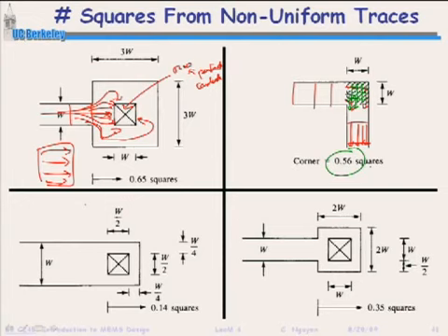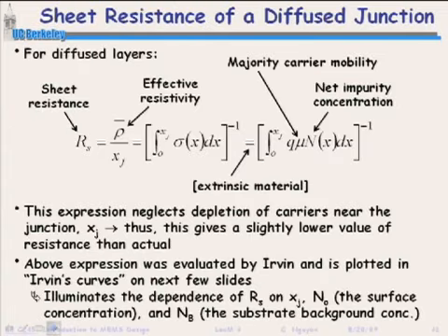But finally on this, that's what I was talking about in the slide before, right? You don't have a cross-section that looks like this. It's not a perfect rectangle. You have a cross-section that looks like this. And in actuality, the concentration gets smaller as you go deeper into the silicon, right? So it's not something where you can get sheet resistance by just calculating depth and multiplying by a uniform conductivity. You have a different conductivity at different depths within the silicon. And so you have to integrate along this axis here.